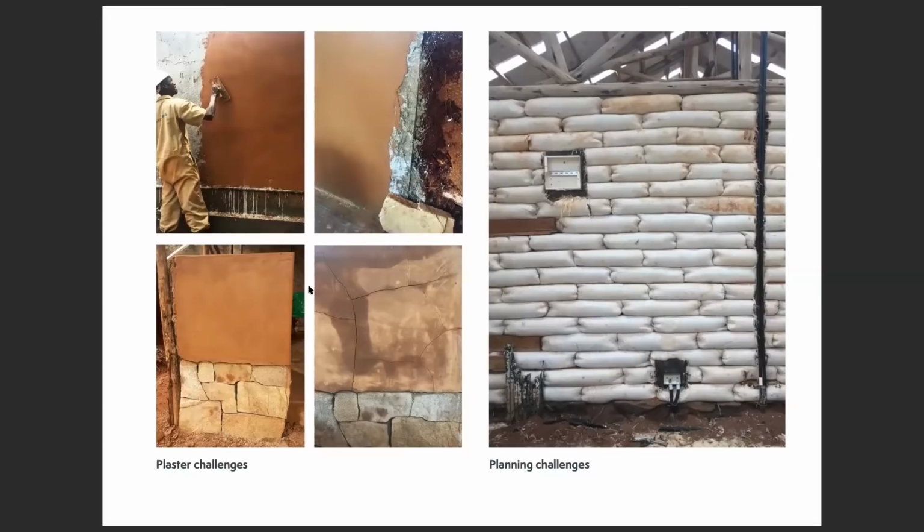So yeah, I've said that we've done quite some trainings. It's important that we have reinforcement, and it's also very, very important that we cure these walls. A bit of a lime cycle is that the lime is of course burned from calcium carbonate to expel the carbon dioxide, and you remain with calcium oxide, and then that is what you actually use to mix with the sand and water to make the lime plaster.